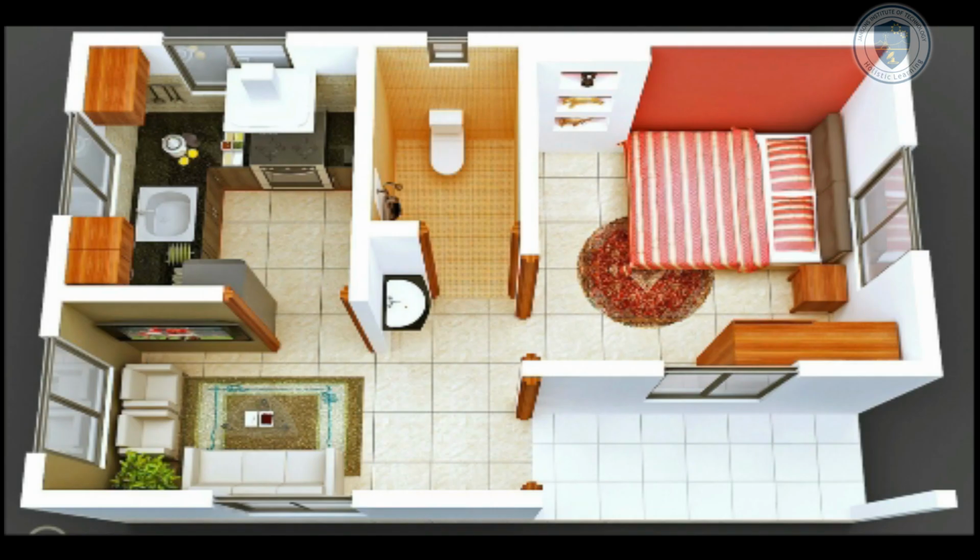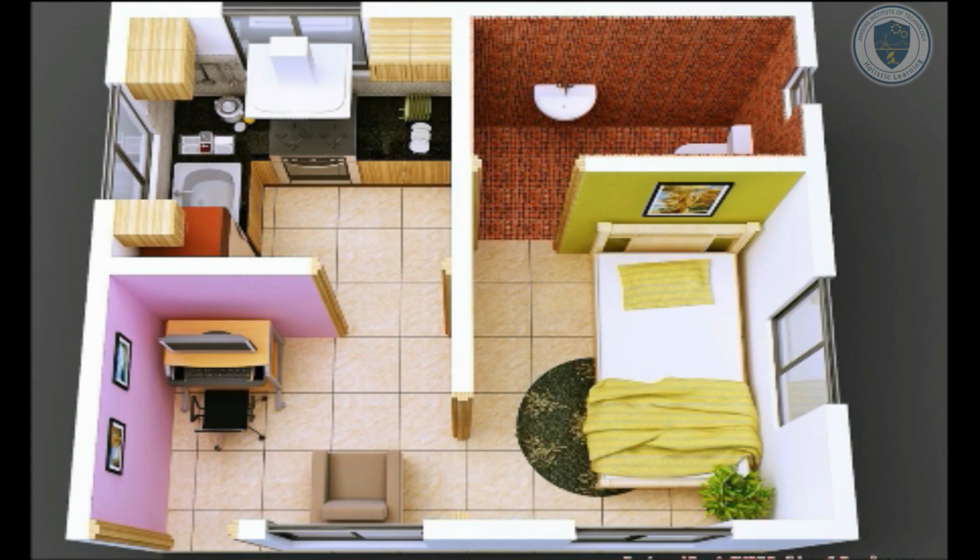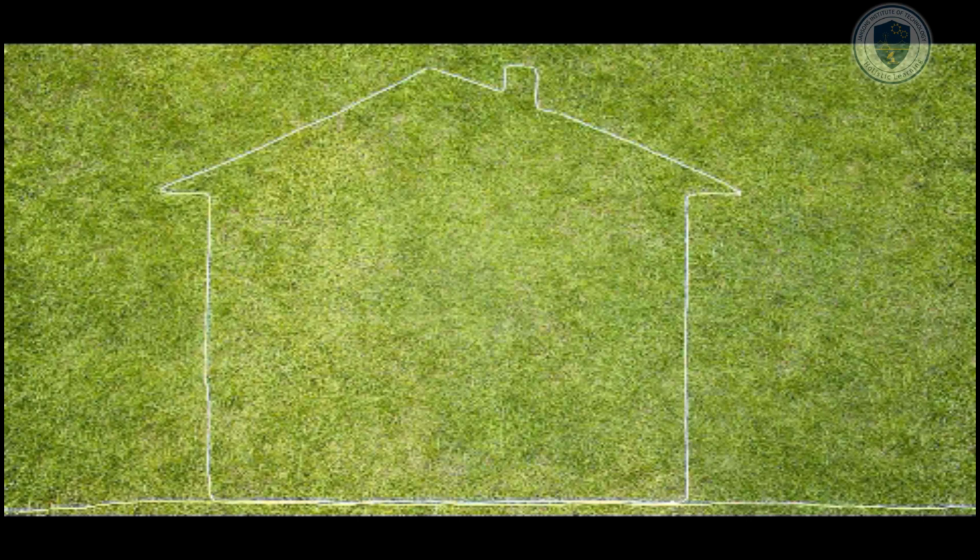Natural lighting in the kitchen should have 600 to 1000 lux illuminance according to BIS standards, which is equivalent to a 100 watt bulb of artificial lighting. Also, exposure to UV rays in the morning time of cooking enriches our food with natural vitamins and nutrients from direct sunlight.